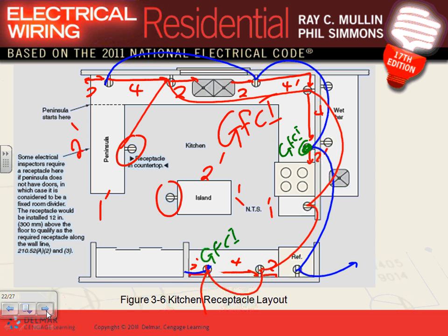I will put two circuits in a garage if I want to wire it, not code. I would do 2 20 amp circuits, feeding at least two receptacles in every wall in the garage, and divide them between two circuits. One of these receptacles will feed the freezer. But code-wise, one circuit.